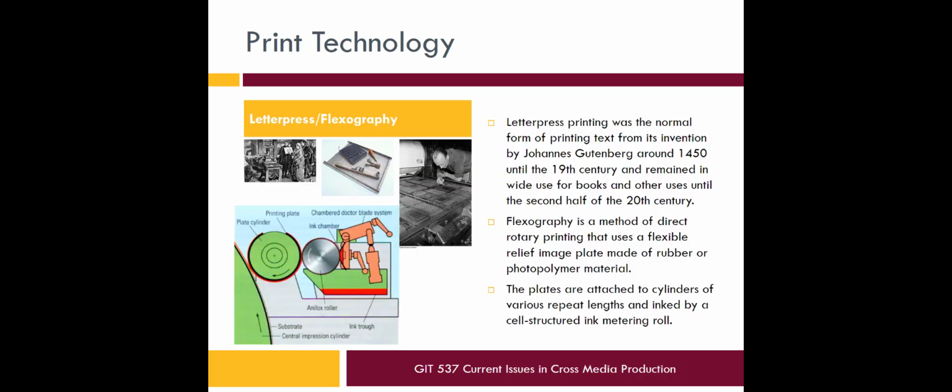Letterpress and flexography are both rather similar techniques. Letterpress is a much older technique of the two. Both of them involve the application of ink to a plate with raised surfaces or a relief image. Those raised inked surfaces are then put into contact with your substrate, paper, plastic, whatever it may be, and the ink is directly transferred onto it using a cylindrical roller. That's flexo.